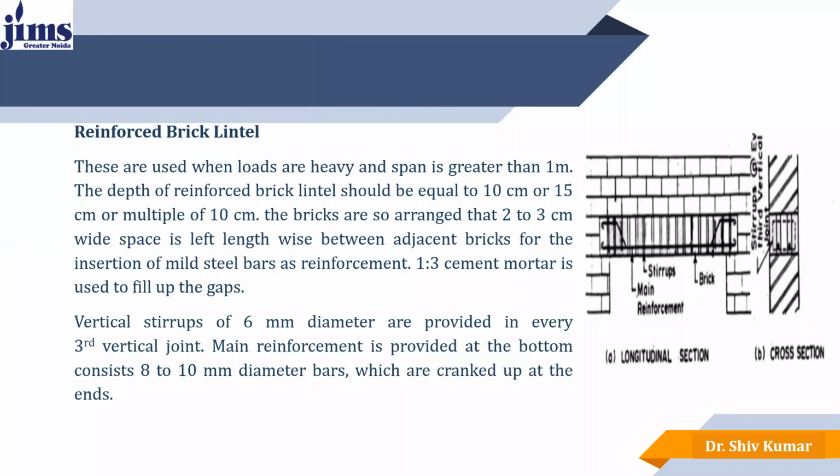The next is reinforced brick lintel. Here we can see that the steel bars are provided in between the bricks to make it reinforced brick lintel. These are used when the loads are heavy and the span is greater than 1 meter. The depth of RCC brick lintel should be equal to 10 centimeter or 15 centimeter or multiple of 10 centimeters.